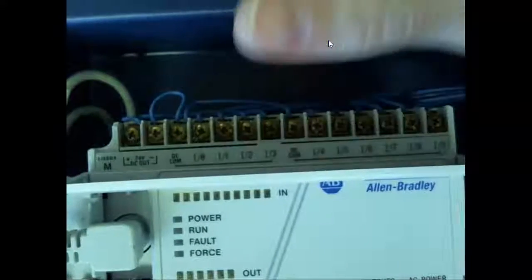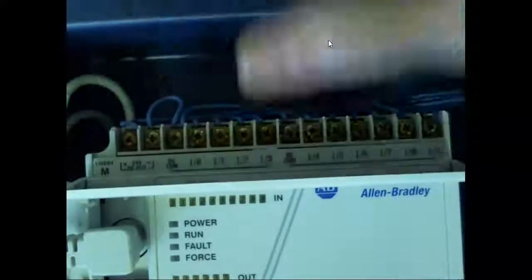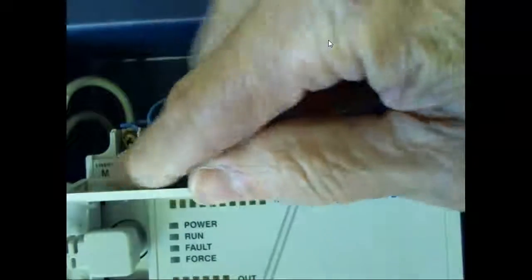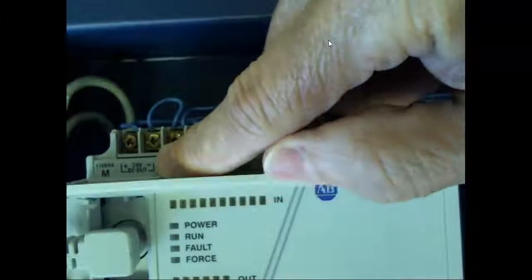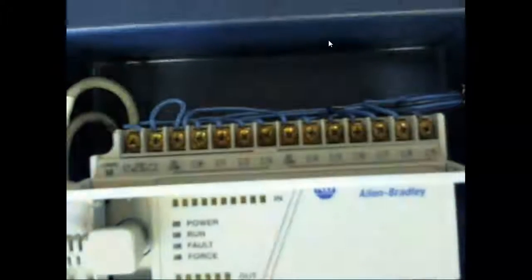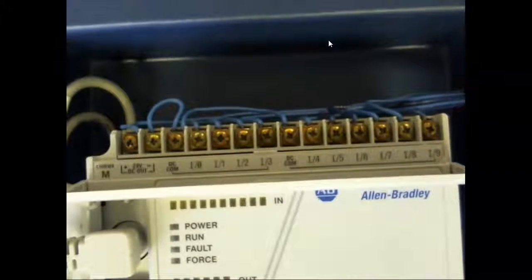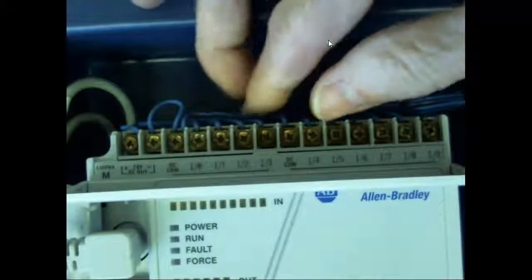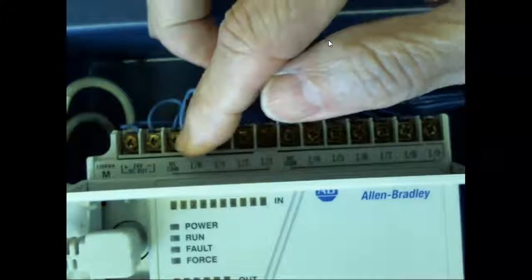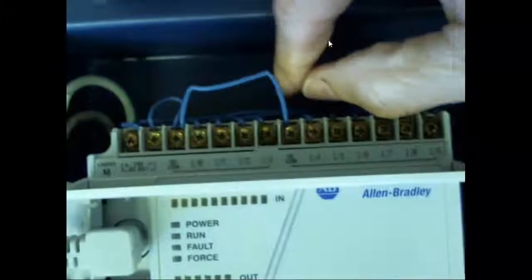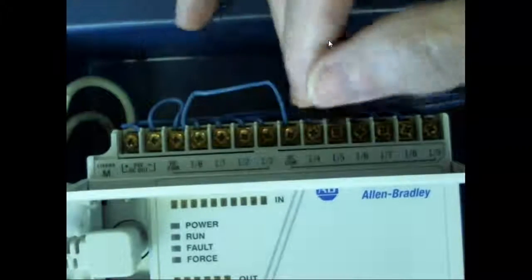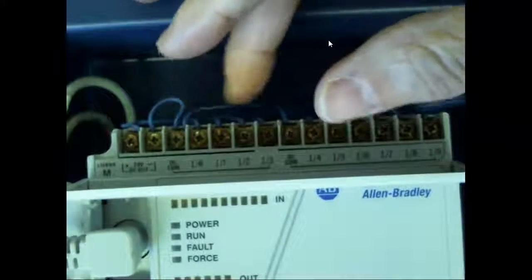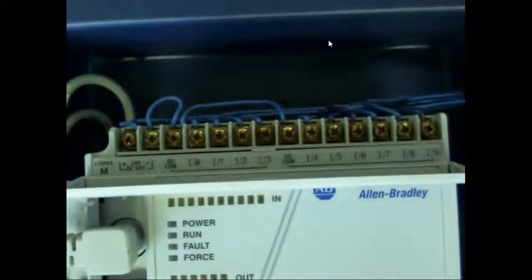Here the power supply is not internal. It has a power supply on it. Here's the output right here. So it says 24 volts plus or minus and it says DC out. Can you see that? Yeah. And then you can see what I've done is I've taken the minus and run it to this DC common. And then we've got this jumper right here that's taking it and jumping down to this DC common. So this guy right here is using the minus as a common. Okay. This guy has relay outputs.